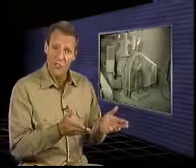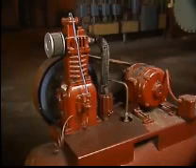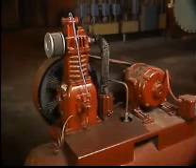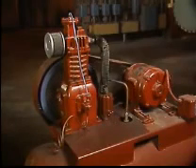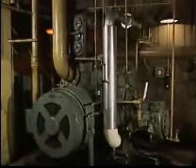Pressure regulating methods range from a simple on-off system to more sophisticated methods, such as the use of inlet valve unloaders. When pressure is regulated by a simple on-off system, a sensor in the receiver controls the compressor's drive mechanism. When the pressure in the receiver increases to a preset value, a signal is sent to stop the compressor. When the pressure in the receiver drops to another preset value, a signal is sent to restart the compressor. Large compressors tend to be more efficient if they operate continually. So one device that is commonly used to prevent overpressurizing the receiver is an inlet valve unloader.